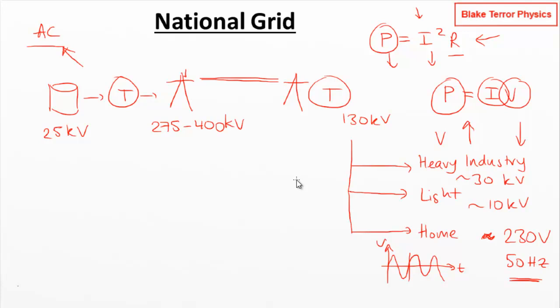Now we don't want to get confused about what these voltages actually mean, because I've seen people look at this equation and say, oh yeah, the power dissipated is I squared R, but we can also write that as V squared over R, and look how high these voltages are, so we're still going to get this massive power loss. Well, of course, you're not looking at the right thing. Remember, this is power dissipated in a component: the component of resistance R, the power cable of a certain resistance, which we said in a previous video might be something like 0.3 ohms per kilometer of overhead power cable.